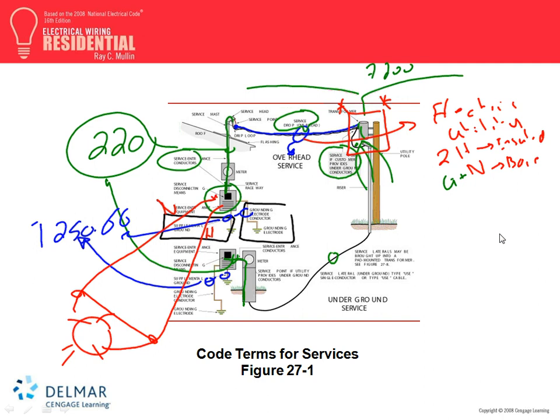And at this point, say it's shorted to ground. At the point here, if they're not bonded, how is the short circuit current going to go back to the source? Say if you have a ground fault here, line to ground. Say that was ground, line to ground. How would the current go back to the source unless you bond them?